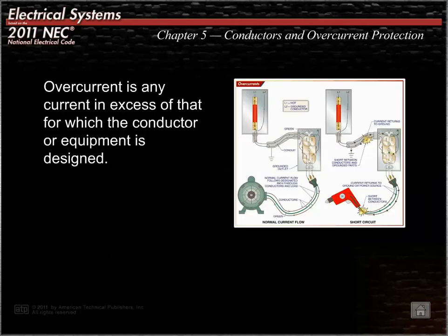An overcurrent is any current in excess of that for which the conductor or equipment is rated. See Article 100. In terms of application, some equipment is designed to accommodate overcurrents for a period of time depending upon the load. Temporary surge or startup overcurrents are common for some electrical equipment like motors and generally have no long-term harmful effects. When overcurrents occur more frequently or persist for long periods of time, damage to the electrical system may occur. Overcurrents can result from overloads, short circuits, or ground faults.